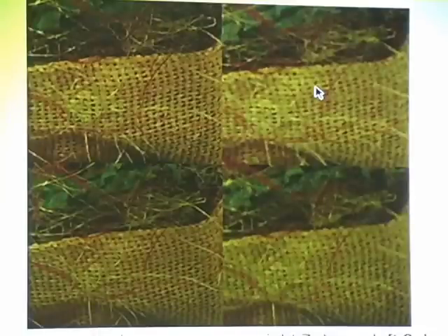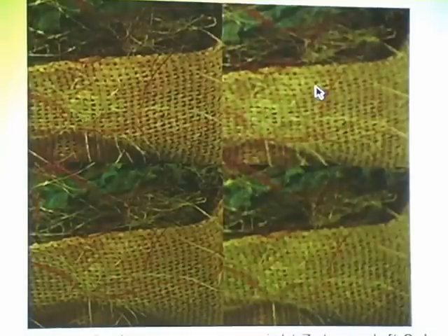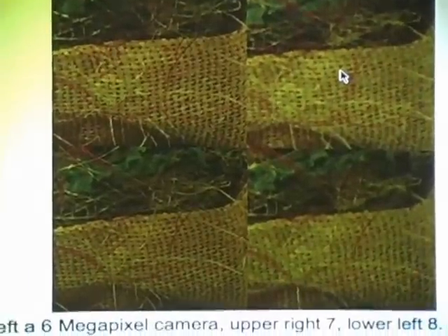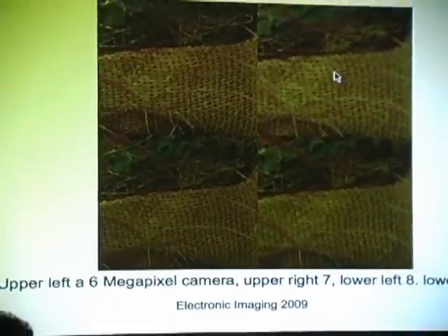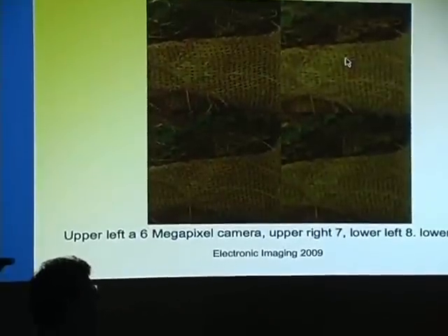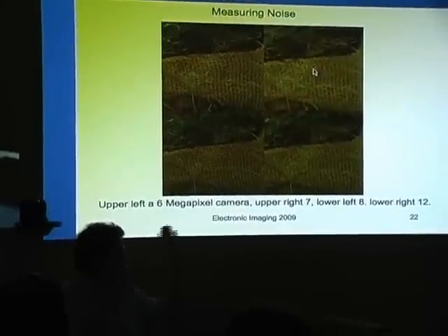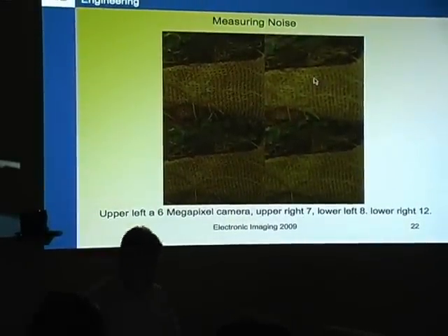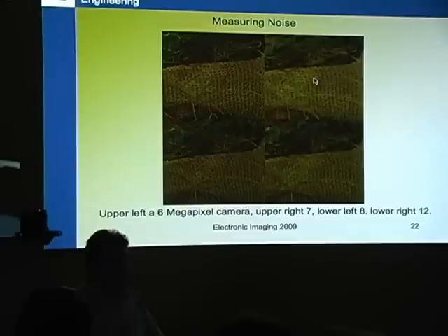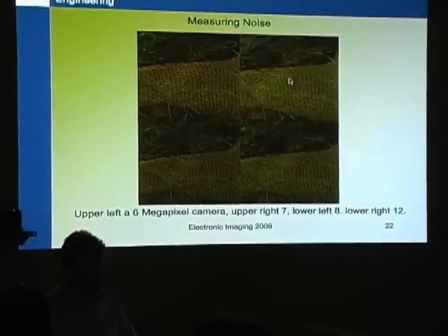So doing the resolution measurements a typical way, we got a good resolution value because these noise reduction algorithms tend to leave all the edges, high contrast edges in the image untouched. So they only affect the low contrast, especially high frequency part of it. So our resolution measurements weren't really able to reflect that loss of fine detail. So we were looking for something to describe and to measure that loss of detail.